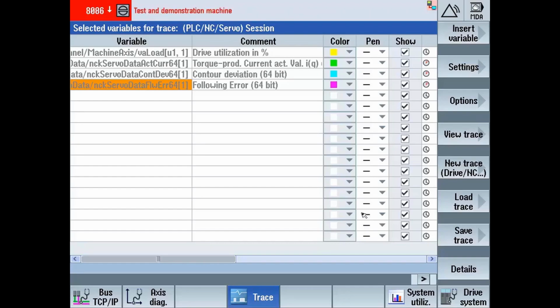The thing that you have to watch with contour deviation is that as a value, the way that the models are run, you should not compare contour deviation from axis to axis. If you're looking at the x-axis contour deviation versus the y-axis contour deviation, there are many cases where that's not necessarily a representative way to look at it. There's some scaling things that go on. And because of the scaling, anytime you make a change to a control loop or change axis, you kind of have to stop using that as a comparison of this versus that.